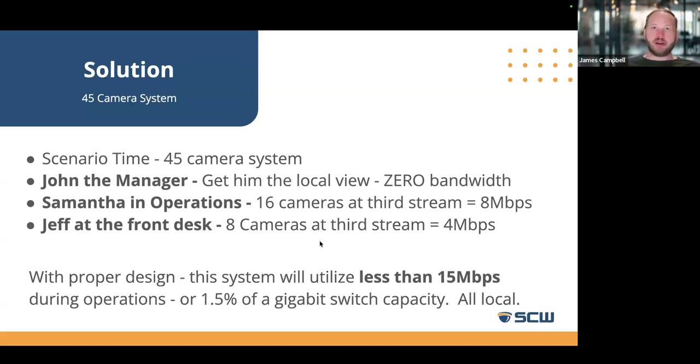What are we going to recommend for that situation, right? To go back to what I mentioned, offer the best solution with the least amount of resources utilized. So when it comes to John, the manager, the guy who wants to have all the video, nice big screen up there, I'm going to recommend let's get him the local view. Because what that's going to offer us, that's the HDMI, by the way, outside of the NVR, is a zero additional bandwidth solution for him. No matter what, that video is always going to be there.